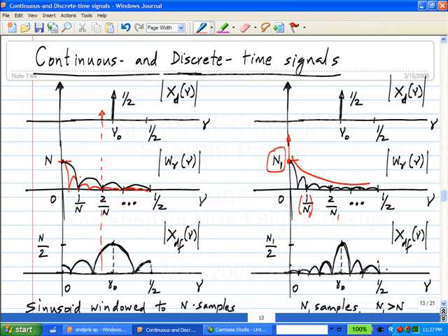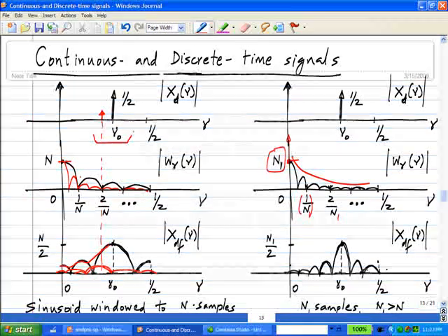Because this has a smaller amplitude, it will be something smaller, something like this. It has to get added to this one. So you may not even realize that there are two sinusoids, because it will look like some smooth stuff like this. You won't even know that there are two sinusoids, whereas it is very obvious from this picture. So basically the effect of leakage is to mask frequency content in other frequencies. That is the problem.